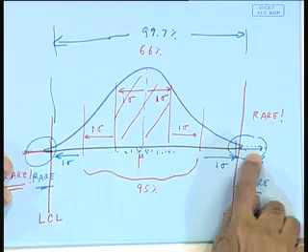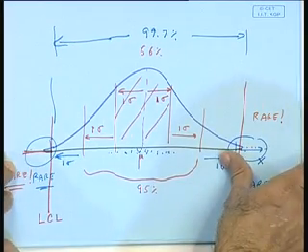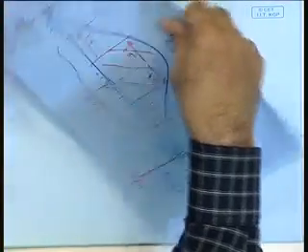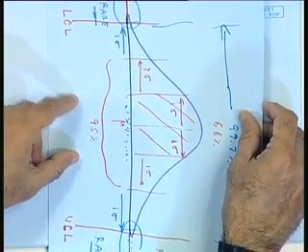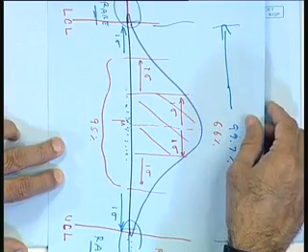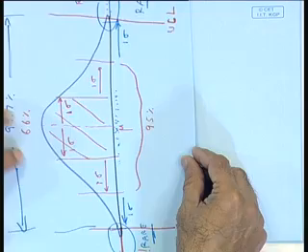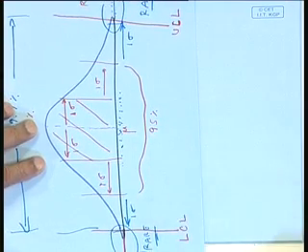But the moment I find 1 or 2 x bar points there, all I have to do to understand this is to turn this sideways, just by putting it like this. Now you can see the upper control limit right there and the lower control limit right there.